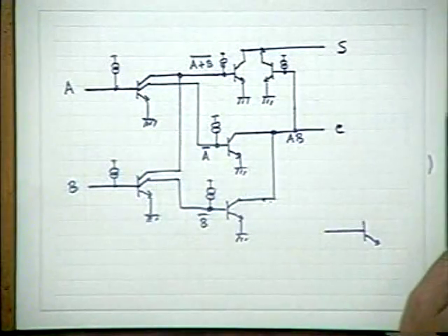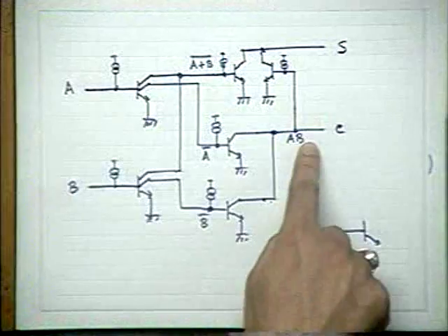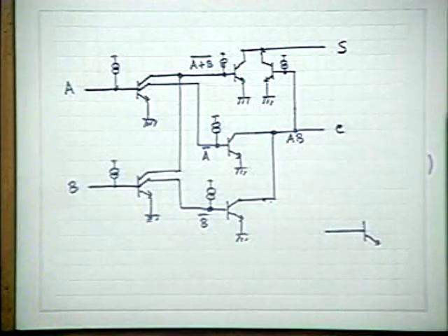Then naturally I have to design a constant current source of the particular value, and connect it to the injector, whatever injector I have shown in the main diagram. That's the thing. But please remember, when we consider a big I2L circuit, firstly we do not show the ground, but please remember the ground line has to be distributed. Is it necessary to distribute the ground line or not?